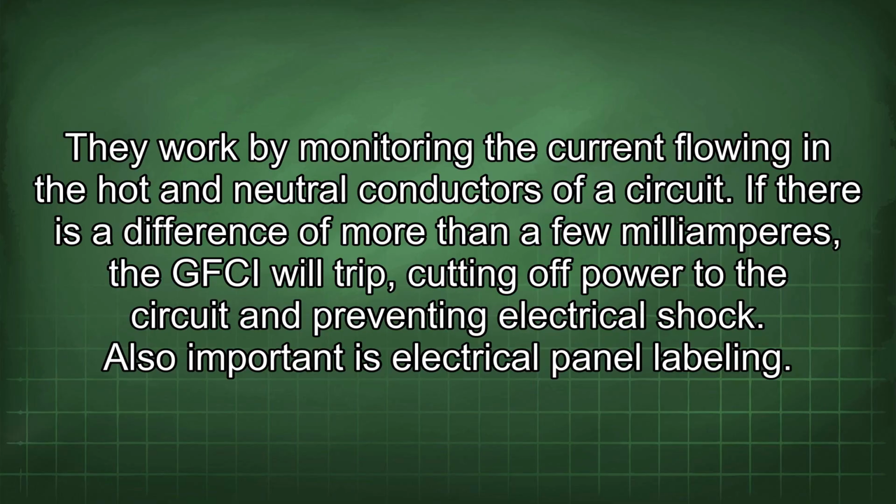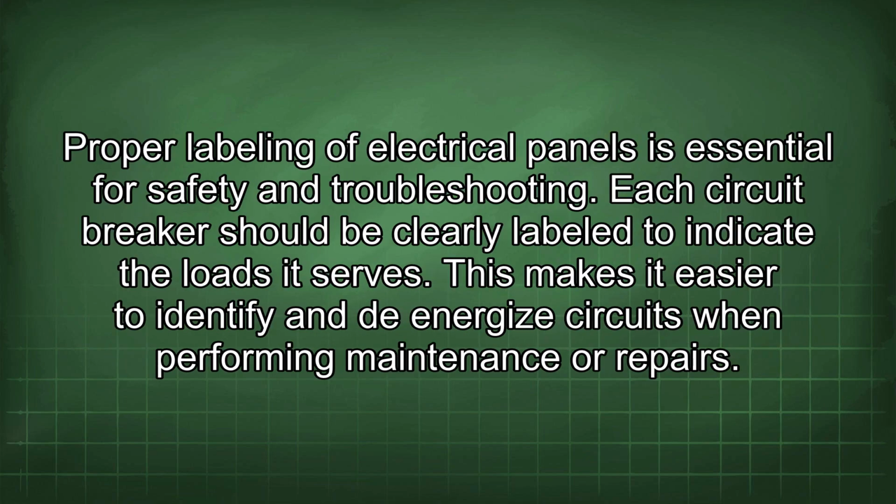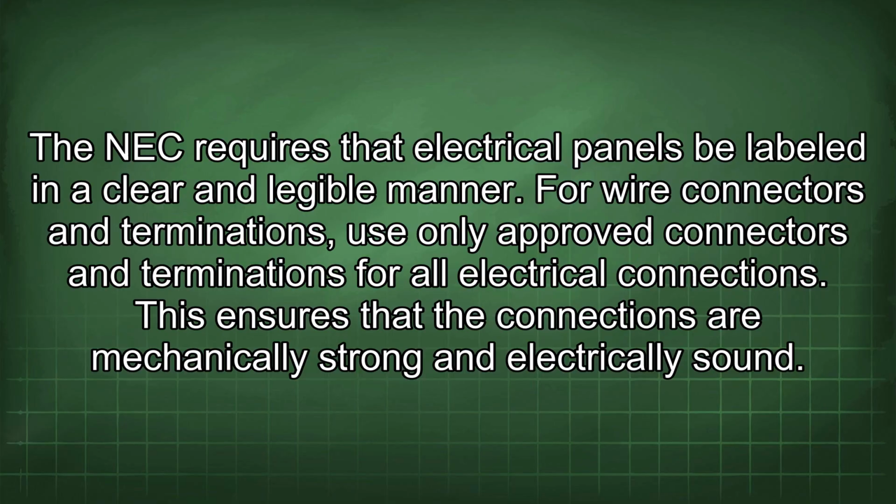Also important is electrical panel labeling. Proper labeling of electrical panels is essential for safety and troubleshooting. Each circuit breaker should be clearly labeled to indicate the loads it serves. This makes it easier to identify and energize circuits when performing maintenance or repairs. The NEC requires that electrical panels be labeled in a clear and legible manner.